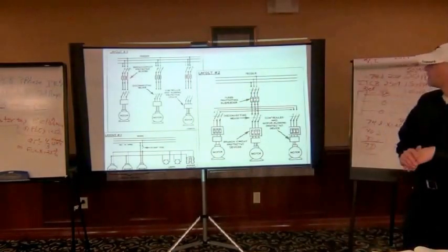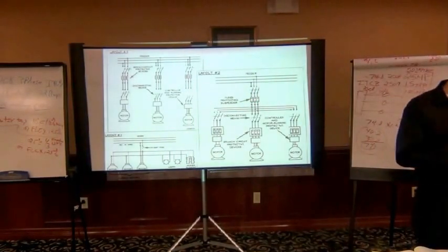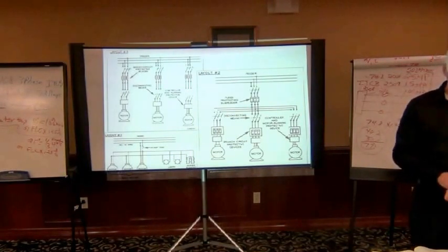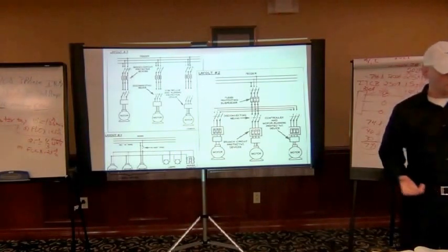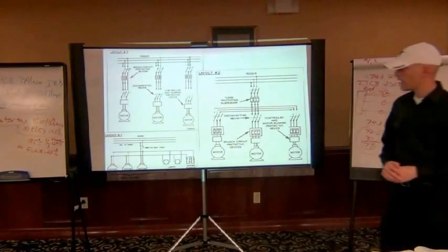Yeah, fire pump motor, that's right. You might just write it down in the bottom there, just put fire pump motor, 50 horsepower, 480 volt, 400 amp breaker. That way if you have it, you have it.